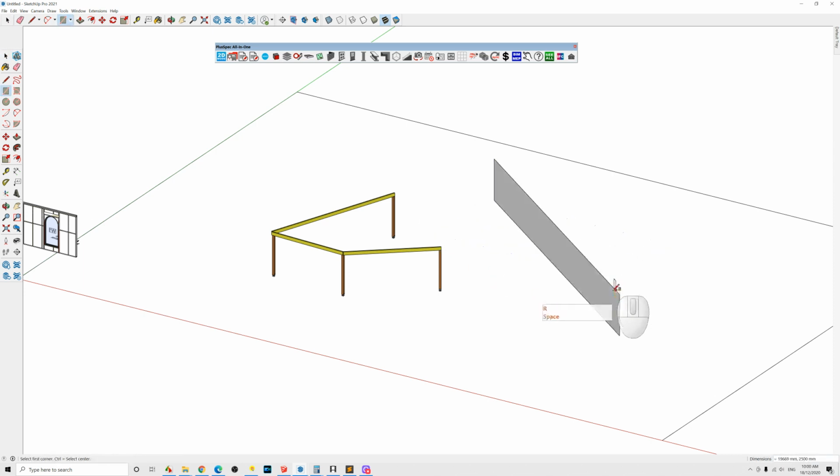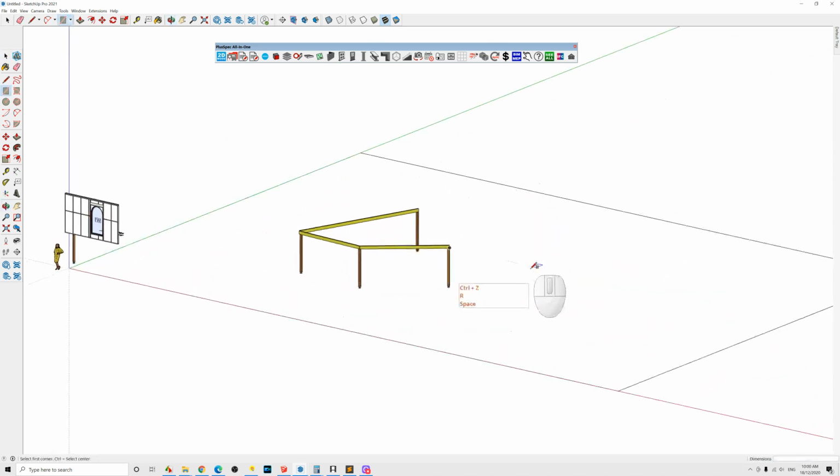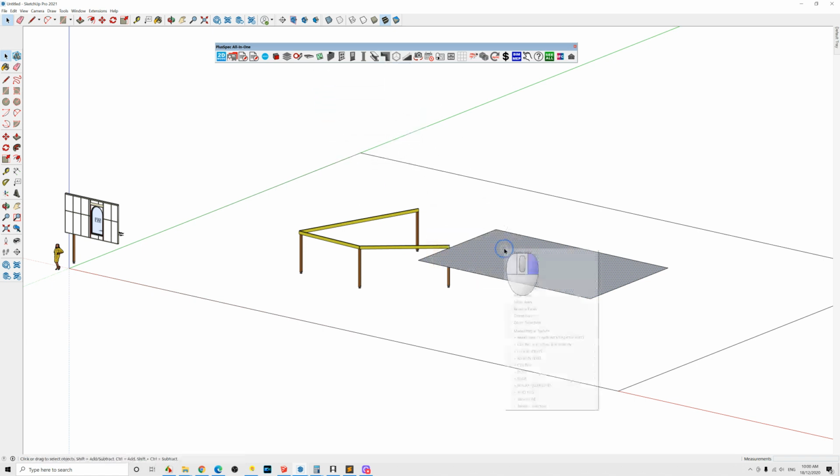Roofing tool, obviously we'll do roofs, and once again inside of the roofing tool you can draw roofs, and you have the tutorials. Obviously I don't want to do that. I use a rectangle tool inside of SketchUp there, select the face. Not only can you click up here, I can actually right click, and you'll notice that it has a whole heap of different options. So I might want to draw floor joists on that SketchUp geometry, assign a level, ceilings, roof, slab, room quantities. I can add a whole heap of things. Everything with a plus in front of it is actually part of PlusSpec or PlusDesignBuild, and that enables you to just get quicker than going up to the toolbar and back all the time.